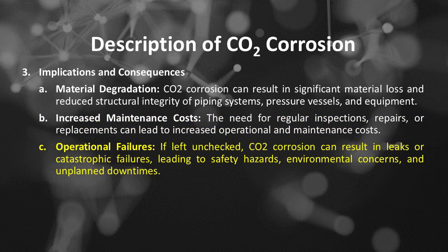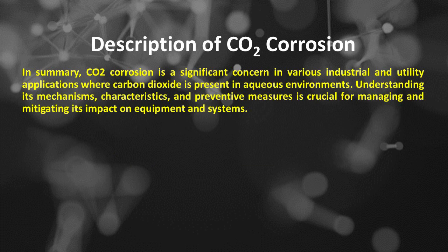Number C, of implications and consequences is operational failures. If left unchecked, CO2 corrosion can result in leaks or catastrophic failures, leading to safety hazards, environmental concerns, and unplanned downtimes. In summary, CO2 corrosion is a significant concern in various industrial and utility applications where carbon dioxide is present in aqueous environments. Understanding its mechanisms, characteristics, and preventive measures is crucial for managing and mitigating its impact on equipment and systems.